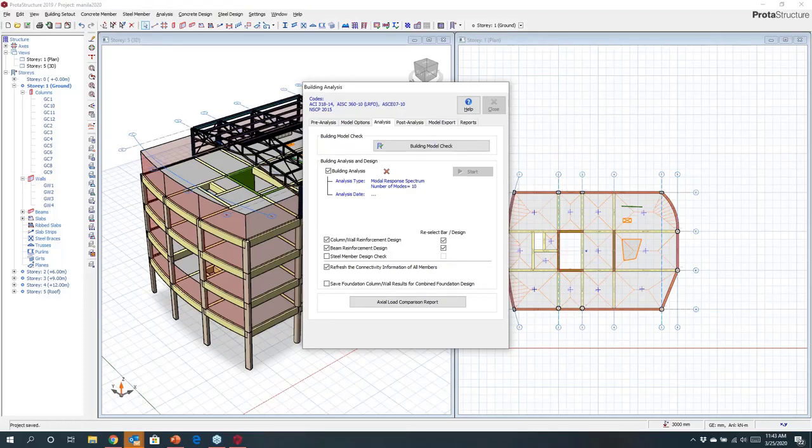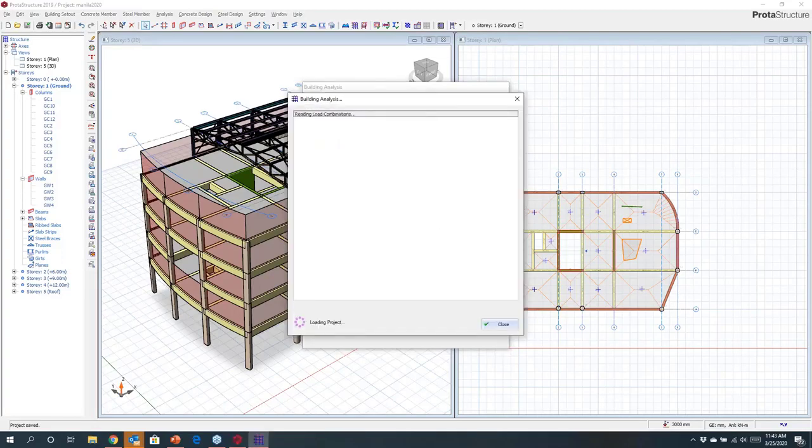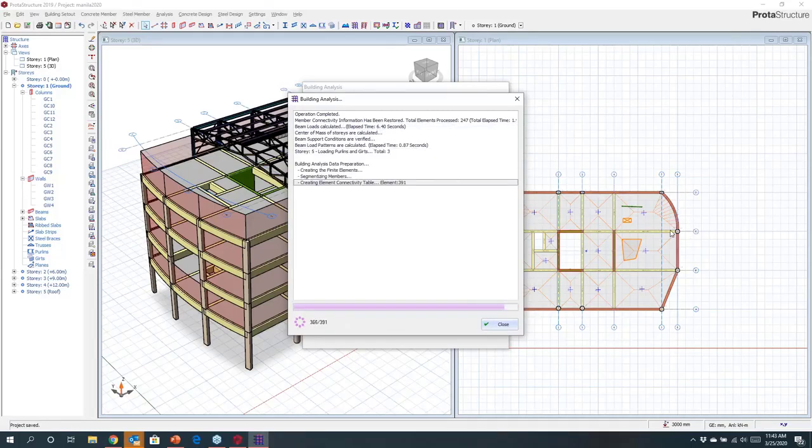Now, this is a physical model, and what we're doing is we're automatically distributing the loading from the slabs to the beams automatically. You might just see off to the right there, you might see that we're actually automatically creating yield line distributions. We can also create finite element distributions. But we're automatically building the analysis here, and it's going through and running this. We've streamlined this process, so you'll find that the analysis is quite fast, and we are moving through and performing the analysis, and then we will move into looking at the design.